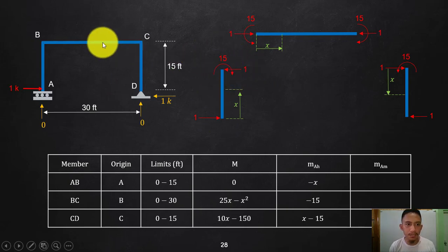And transfer this one, since there are no external loads that will affect that one. This will be originally clockwise, that will go counterclockwise. To the left, that will now be to the right. And then transfer that on the other side, since there are no external loadings here, that will just be equal with each other but opposite direction. So that is to the left, that is now clockwise. Again, there is no external loading at that point, so that will just be transferred. So from clockwise, it will go counterclockwise. From left, it will go to the right, and then of course, there is no external loading.